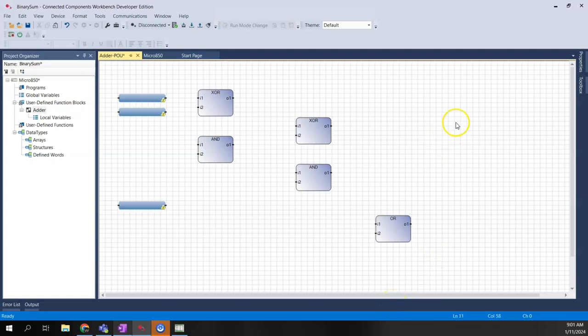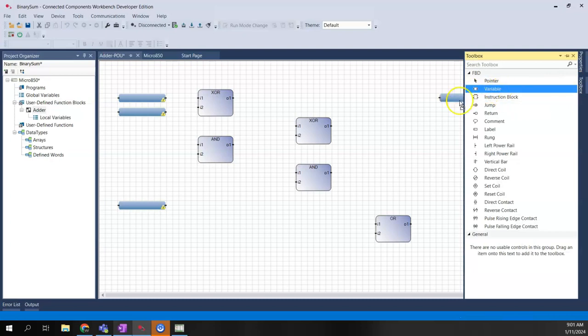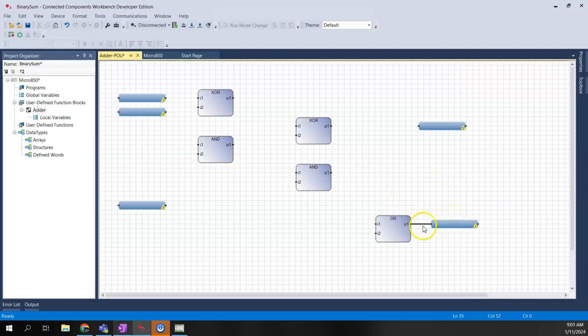All right. And then, of course, we're going to need two more variables at this point. We're going to need an output, and we're going to need this carry out. All right. So the carry out actually connected there, so that's fine. The sum, basically the output of the second exclusive OR gate, will go to the output, or the sum. So the input will go to the first exclusive OR, and then we will also combine the input to the AND gate.